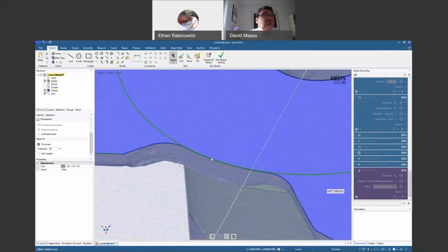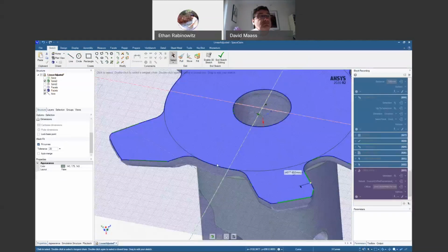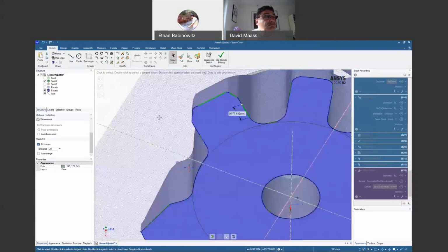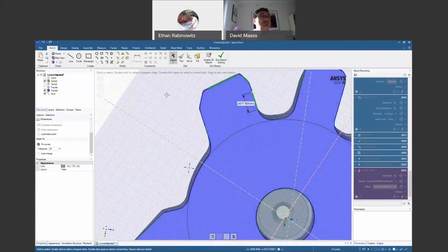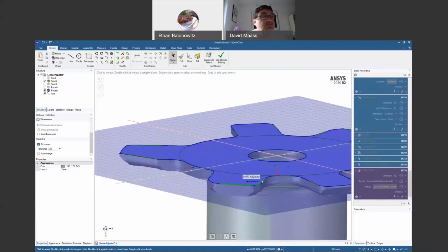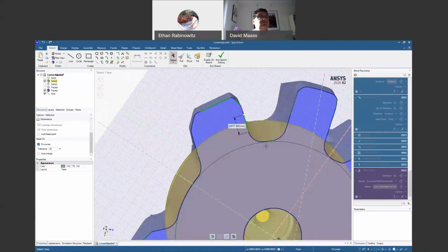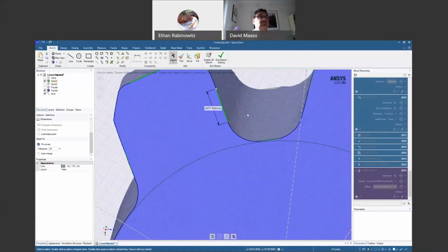I'm just thinking about the intersection here of everything. I'm not sure our cylinder is quite big enough now, but I think that should be an easy adjustment. So basically, I'm going to ignore these rounds. I'm going to model the tabs without the rounds, and we'll add the rounds with the pull tool.